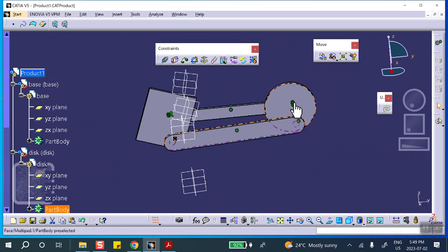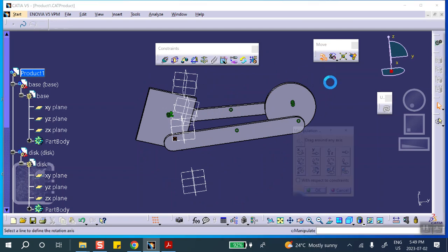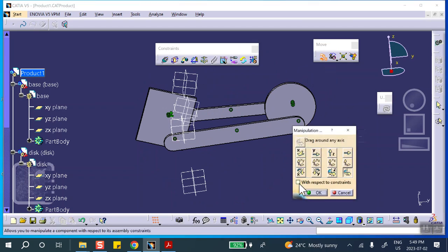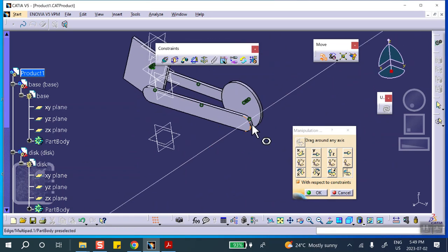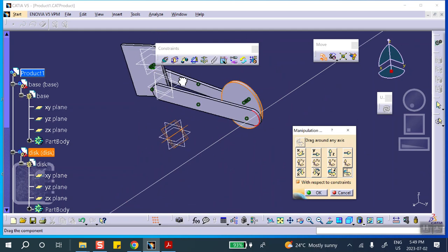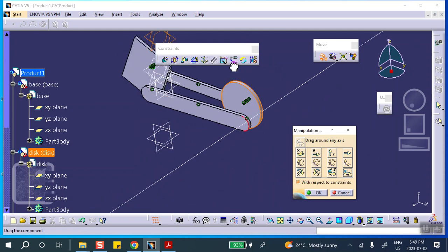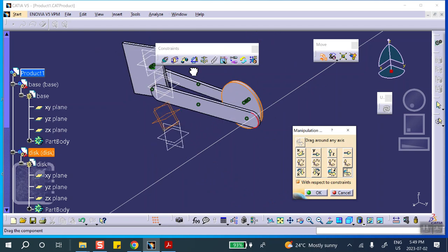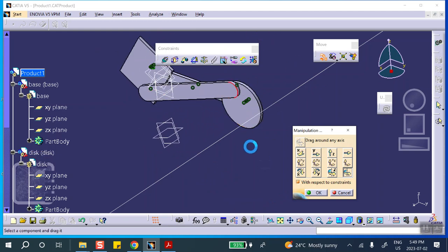Now we can always check, okay? So let me go here, check this box, rotate about, how about rotating about this axis? Let's try it. This should go the way it's supposed to. Oh, here. You see this? That's a 4-bar linkage. This guy rocks. This guy goes 360 degrees continuously. Cancel that.